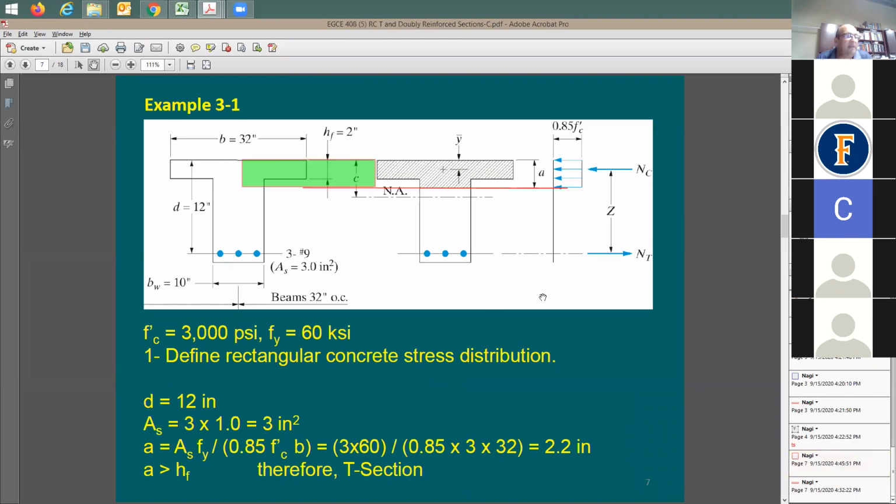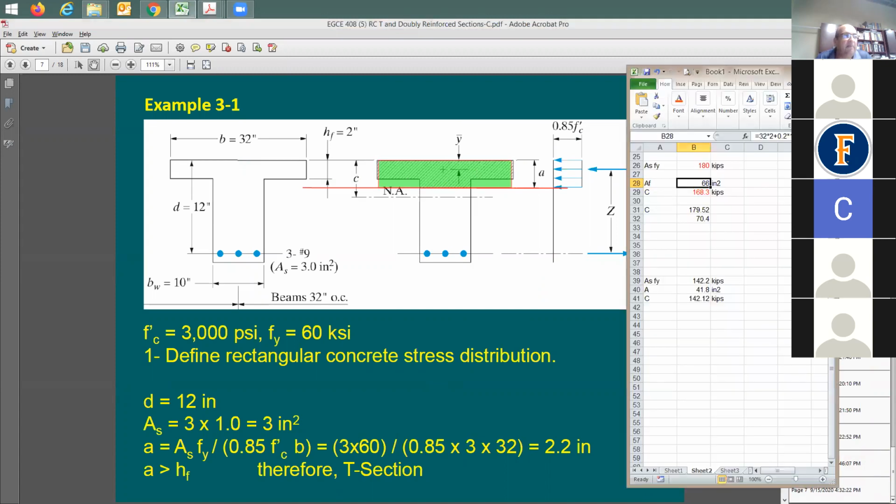So the problem in my assumption is that I assumed all of this green shaded area is going to be exposed to compression. In reality, I don't have this piece here. Look at the difference between the hatching and the shading. It's going to be this little bit of an area here, right? This here causes the discrepancy in my analysis. This is why in the tension I'm receiving here 168, because I took this out. I took this little area, the difference between the shading and the hatching, I just ignored it. I just took it out. This is the reason that my analysis here is incorrect.